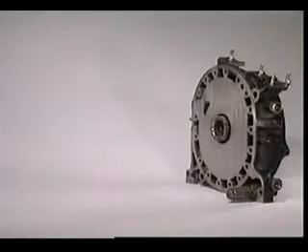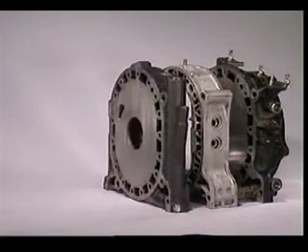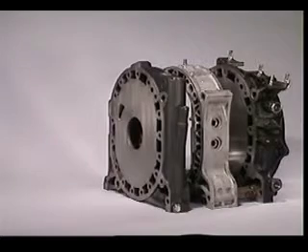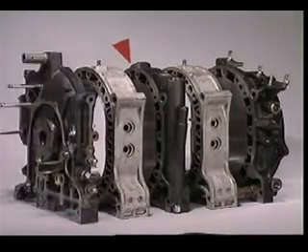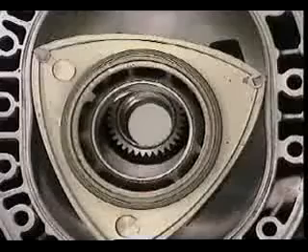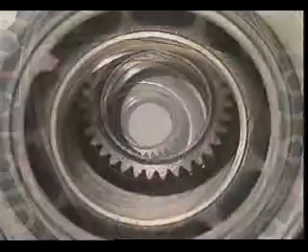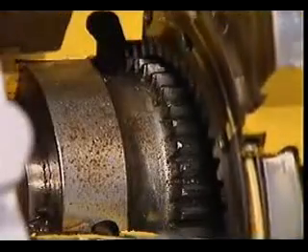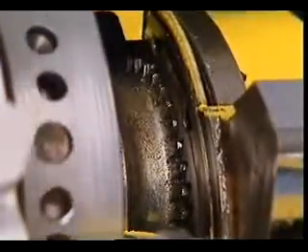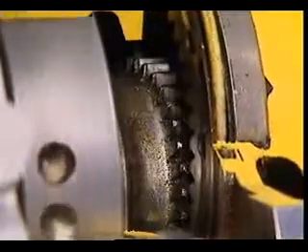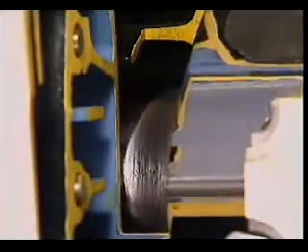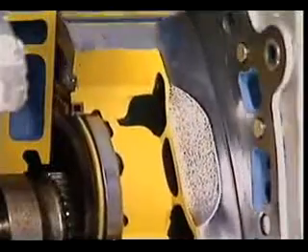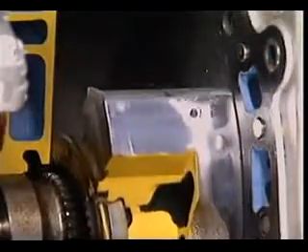Front and rear housings, or side housings, are bolted to each side of the rotor housing. If it's a two-rotor engine, there is an intermediate housing between the two rotors. An internal gear in each rotor meshes with a corresponding stationary gear in the front housing and rear housings. When combustion occurs, the meshing of the teeth forces the rotor to walk around the stationary gear. This combines with the eccentric shaft to make the rotor follow the curved surface of the housing, and it gives the rotor planetary motion.